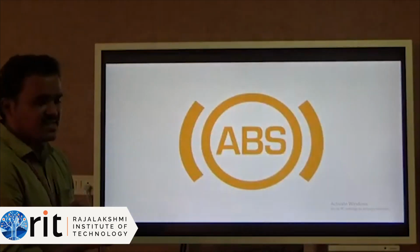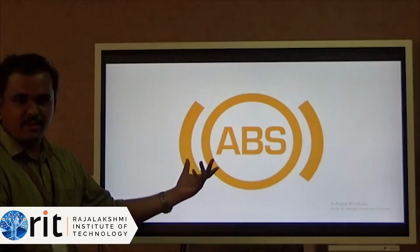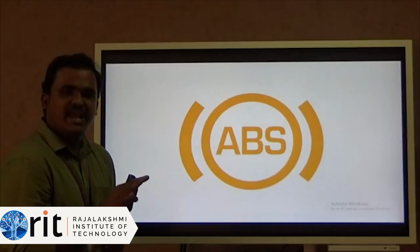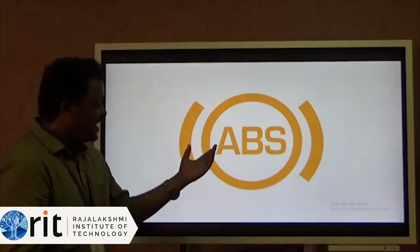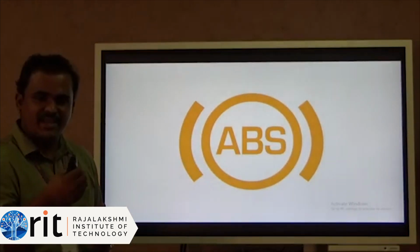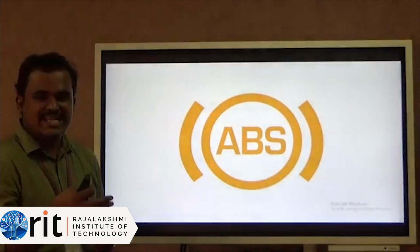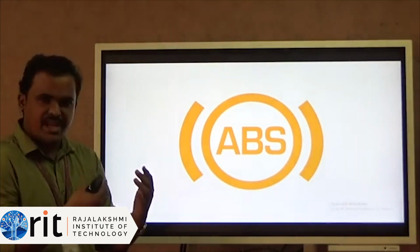The next one is ABS. As you all know, this is the symbol for the ABS in your vehicle, the anti-lock braking system. In a normal braking system, when the brake pedal is pressed, the brake is applied to the wheel abruptly. This ABS system acts such that there is a modulator unit in the system. The modulator unit will send the braking input in separate gaps. It will apply the brake, then give some idle time. Again brake, again idle time.